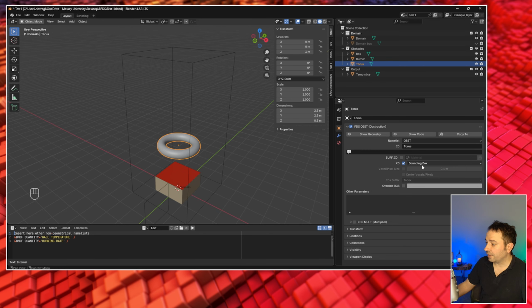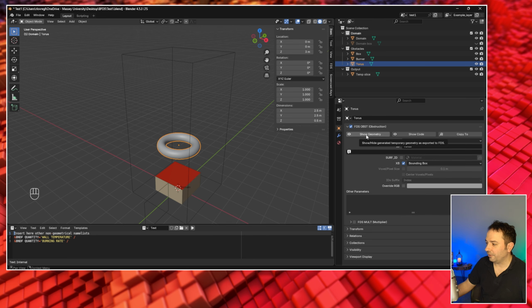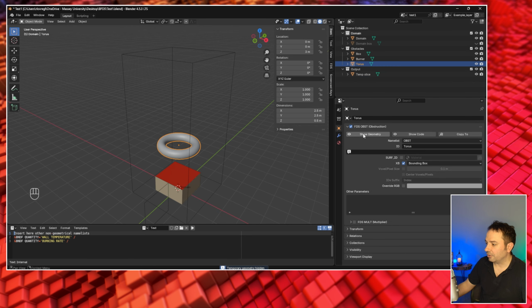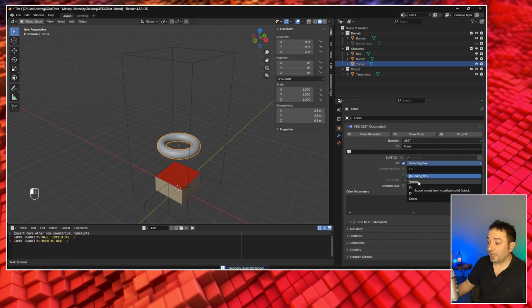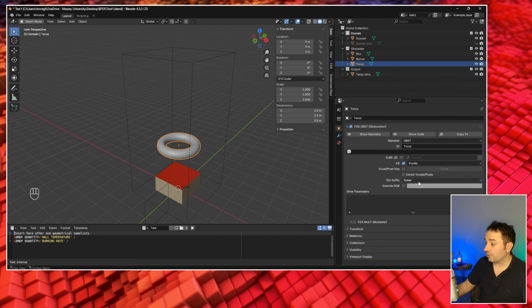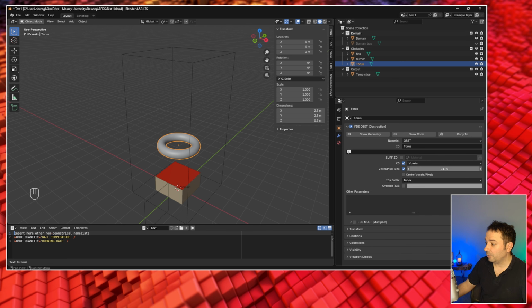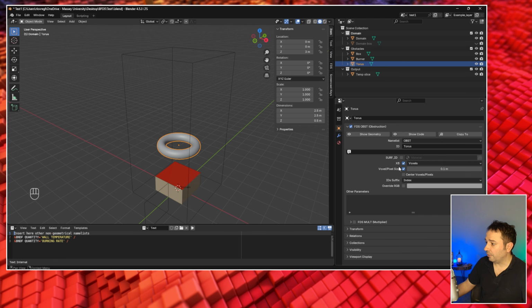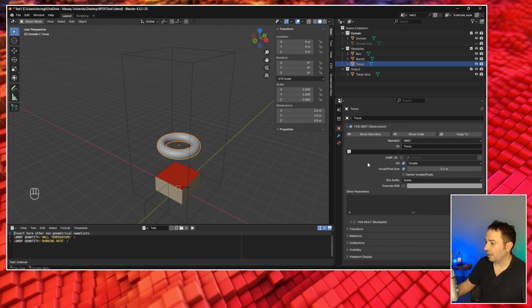And if you use it as a bounding box, you will see that it's not gonna really be useful for us. In fact, it's gonna be converted just into a box. So that's not what we want. The option that back in the day was the only one available was to voxelize it. If we press voxel, we can even define the resolution. The grid resolution that we have already for our mesh is 0.1, so this resolution is aligned.